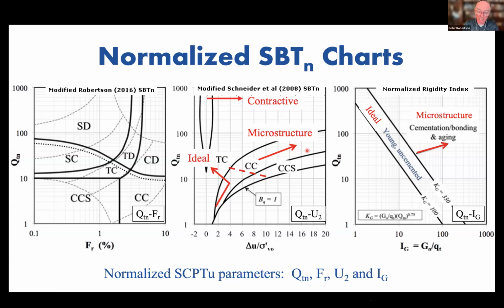So that's the updated charts. They're becoming very popular and they're very useful. But to use them in their entirety, you do have to have shear wave velocity. So you've got to have tip, sleeve, pore pressure, and shear wave velocity.